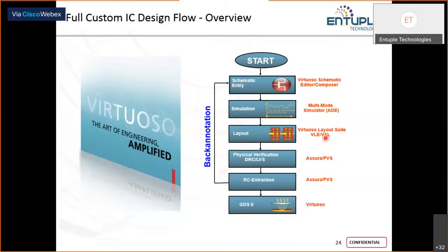The Virtuoso layout editor will help you in capturing the layout. Then for physical verification, to check the design rule compliance and to compare your layout and schematic, you have Assura or PVS. Assura is for higher technology nodes, whereas PVS is for lower technology nodes.